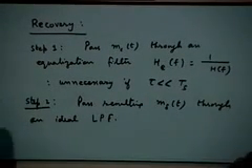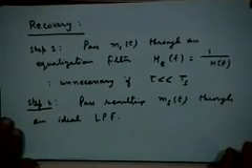Any questions here? So that is all there is to pulse amplitude modulation. Pulse amplitude modulation in summary is essentially flat top sampling. So just like you recover the signal for a flat top sampling case, you are doing the same thing here, nothing more than that. In a flat top sampling case, you do require an equalizer followed by an ideal low pass filter.